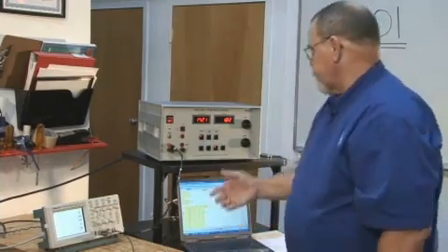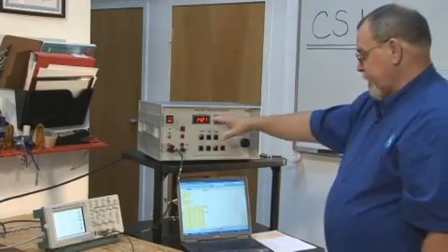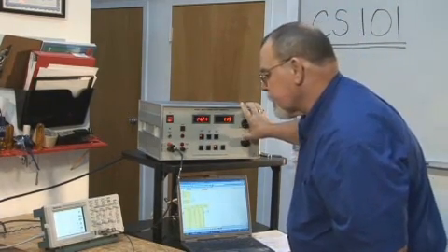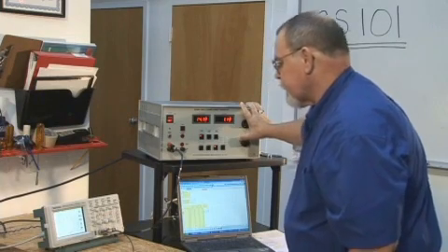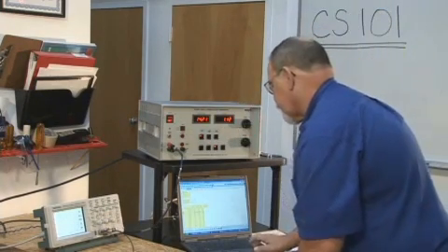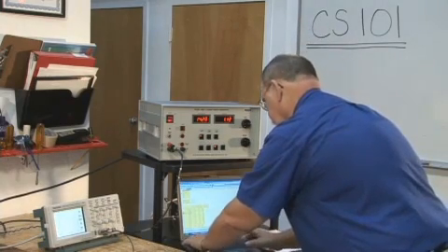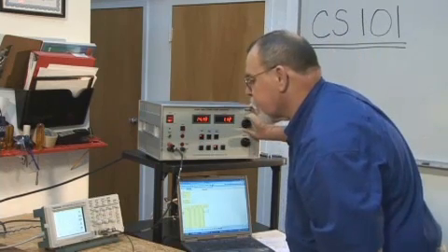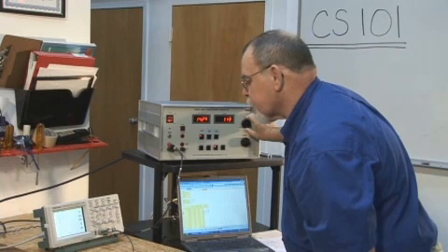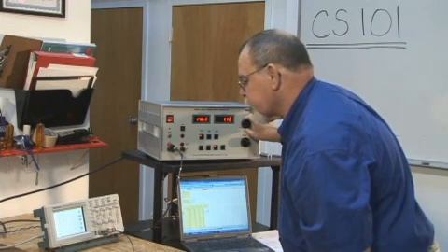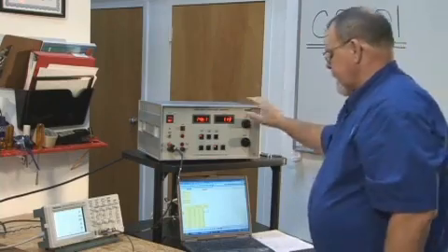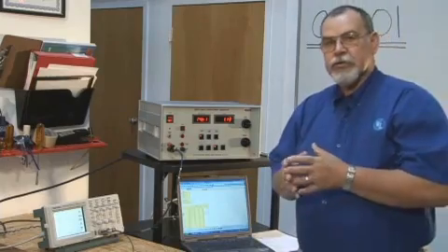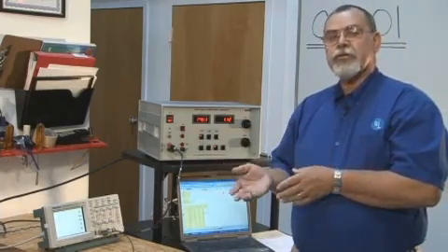I still have my 6.32 volts with the right level at 14.2, so we're going to continue the frequency sweep until we lose below 6.32. And there's the point where I did that. So my next frequency point of interest is 1.12 kilohertz, and I have to increase the voltage now to produce greater than 6.32, and I usually go to 6.4 roughly, and now I'm maintaining a 14.6. This process continues until we get all of the frequency range accomplished.